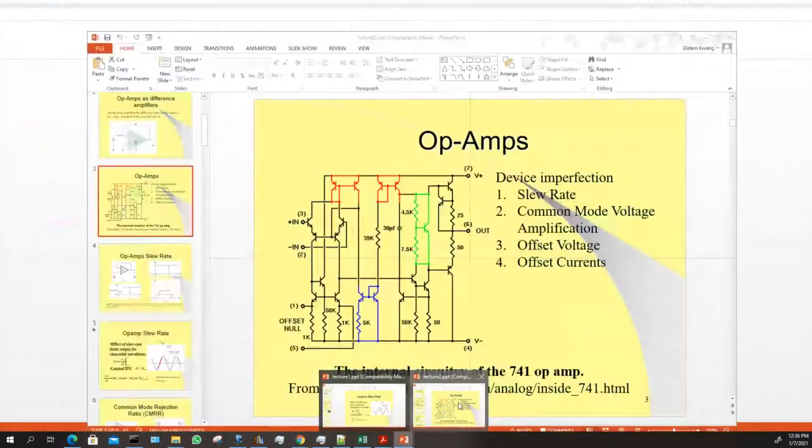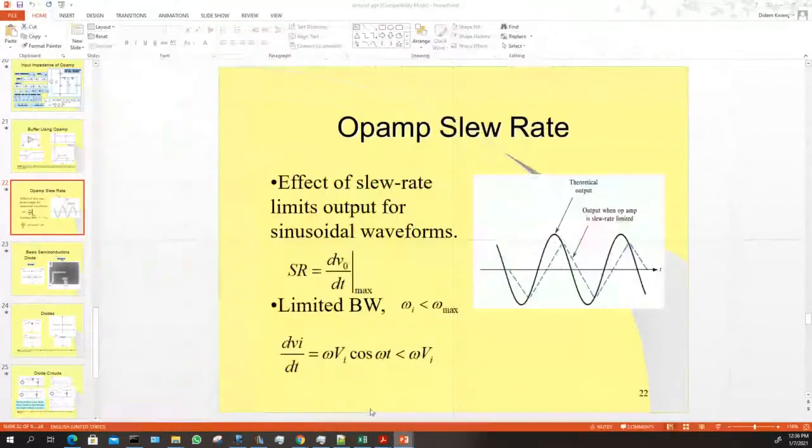But another analysis is the transient analysis. And the reason you do a transient analysis is stuff like this. Can I see how quickly this system is adapting, how quickly those capacitors are loading up with charge, and what the exact output looks like in the time domain, because it may be different from what you're expecting.